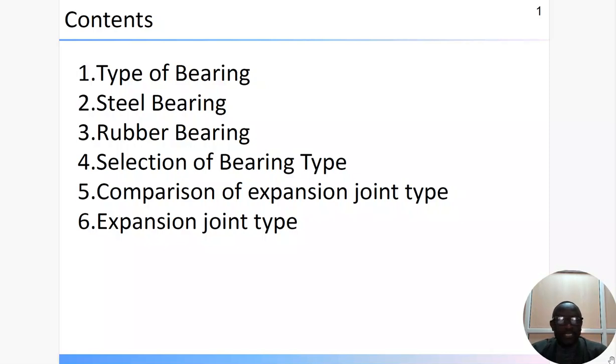I think in the response we noted that bearings are manufactured by specialist firms like Maurer, Freyssinet, VSL, and others. Normally engineers design the bridge decks, get reaction values for dead load, live loads, and other applicable loads, considering also the deformation and other things. Those are the information you supply to the manufacturer of the bearing, and they tailor the bearing to that particular bridge.